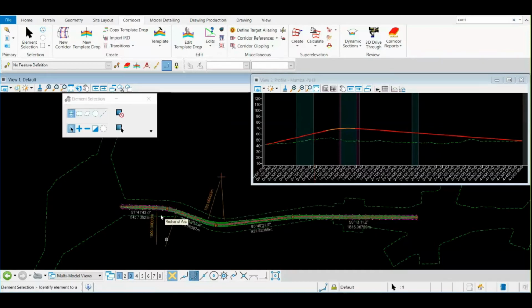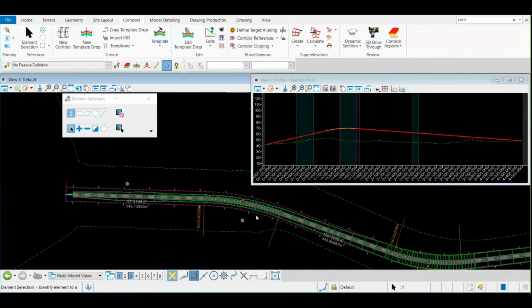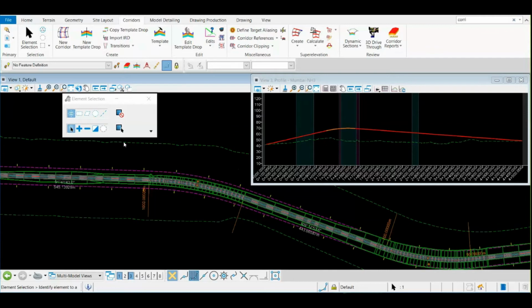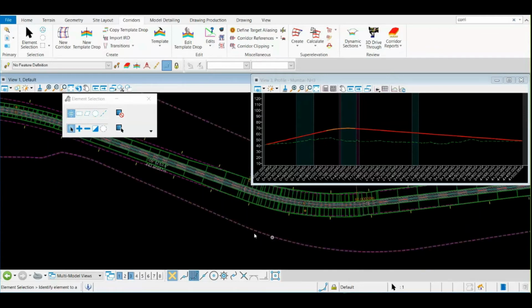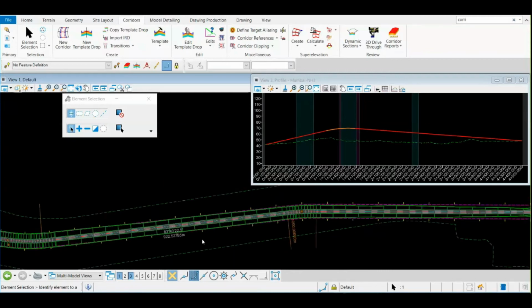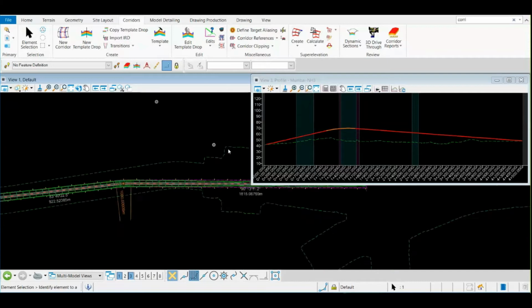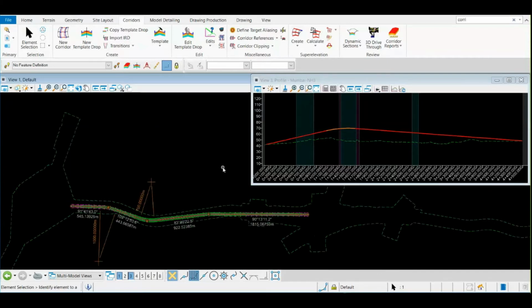If you notice the change, there are some green meshes. Basically, these are denoting your embankments, also at this curve location. So this confirms I have successfully placed my template over my center line. What is the significance now? Till now, whatever I have done, now I am good to go to cut my dynamic cross sections, to see my corridor quantity reports. Also, OpenRoads Designer itself has created a 3D engineered model.